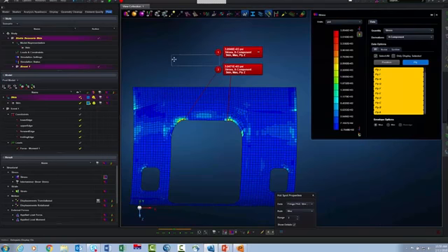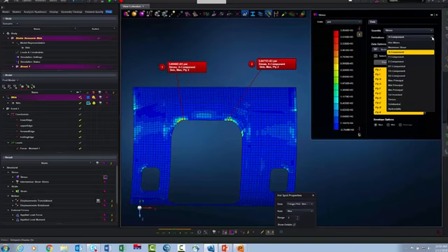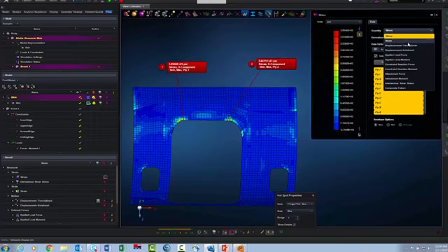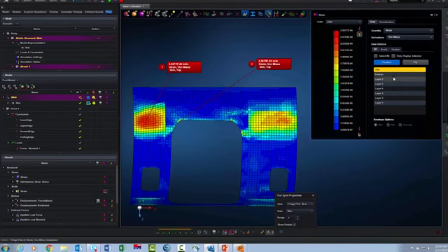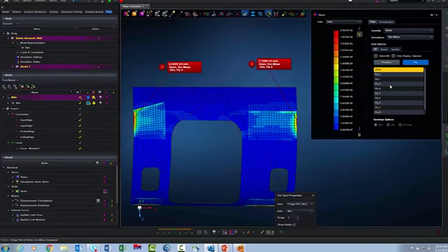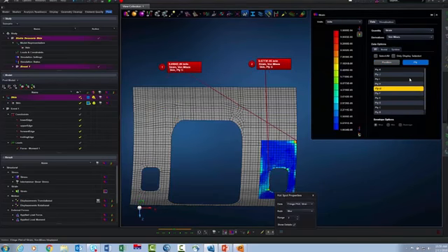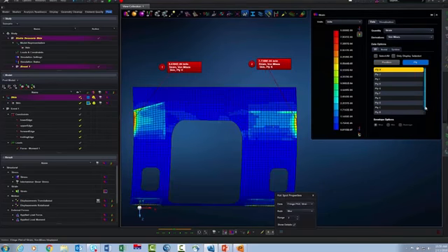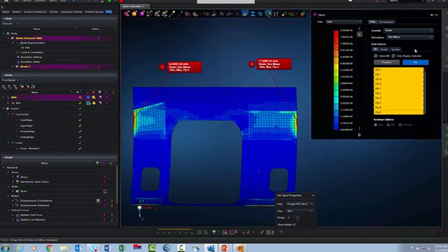So I see what the worst sigma x or the fiber stresses are, which ply, which locations in this particular case, all right? I can also look at individual components, you know, warp and weft and a bunch of other components. I can also look at strain if I want to, okay? Once again, I can look at this on a ply by ply or layer by layer basis if I want to, okay? Or I can look across all of them if I want to quickly identify.